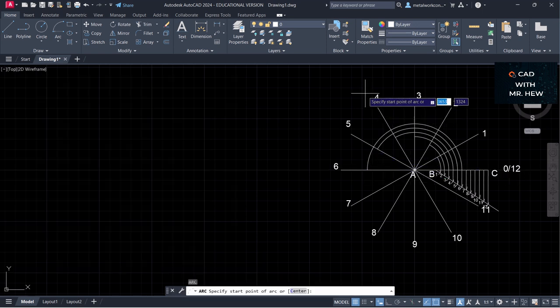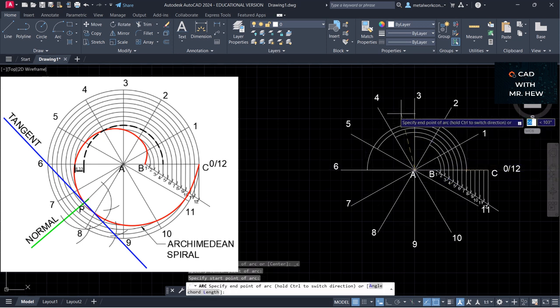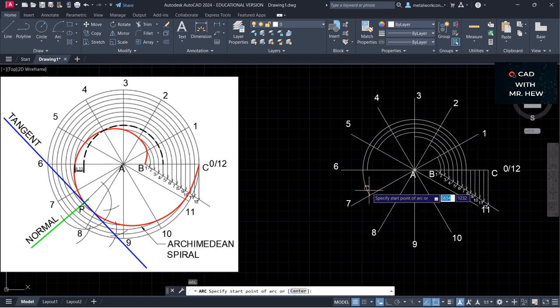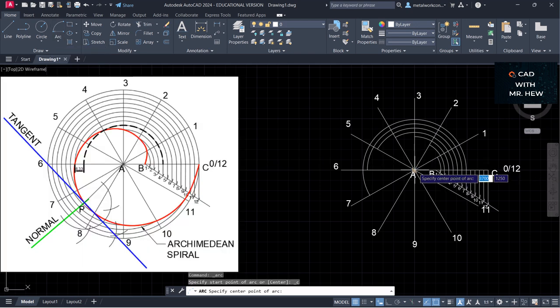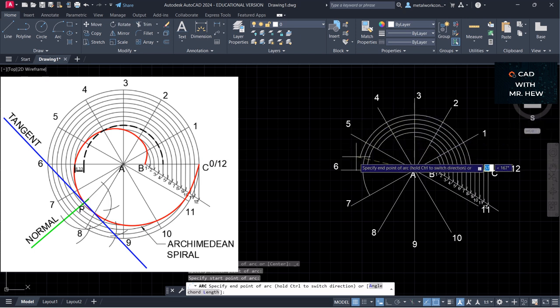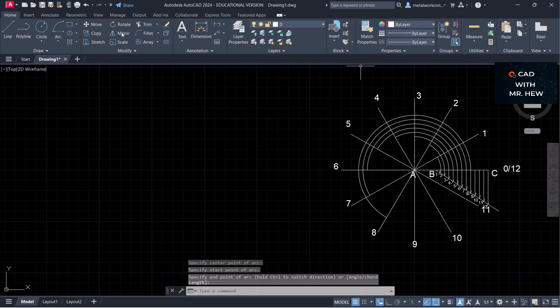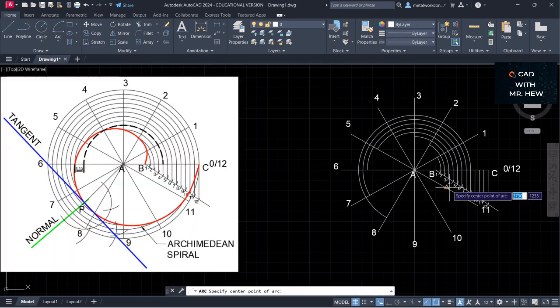All right, so good job if you're following along. And we're going to repeat the process for 7. So we're going to go center at 7. I'm going to come around. So this will be a compass arc, okay? Good job. All right, so we're going to come around. I'm going to carry around 8. So we're going to go 8. I'm going to come around as easy as this. So you would take a compass if you're using the traditional instruments, and you would mark the arc coming around. Okay? So center, start, end.